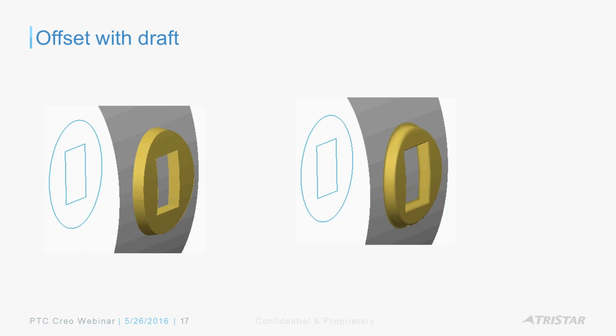And there are quite a lot of surfacing tools, but if you want to create an embossed feature like this, for example, it's very quick and easy on a curved shape or even on a flat surface. You can project a sketch, and at the same time offset just within that projected area of that sketch, and then add a draft angle and add rounds or make it tangent. So this is quite a powerful feature in surfacing if you have not used it before.